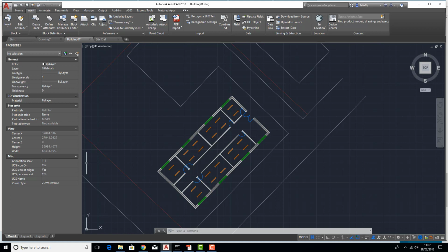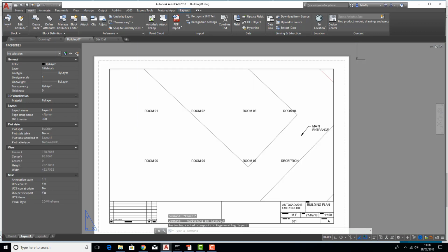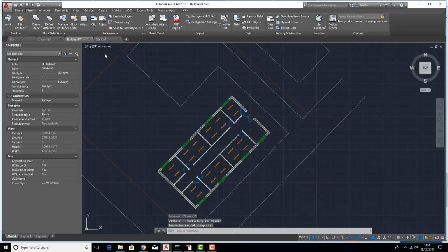Then you can create whichever drawing you want by using those Xrefs, using layer styles, turning things on and off in viewports or in the model, and adding text on the paper. But you would do that by using a combination of Xref models. If you go into a company where they work that way, the best way is to see it working for yourself, and it will become clear. It's quite a good way to work. It does cut down on sizes.